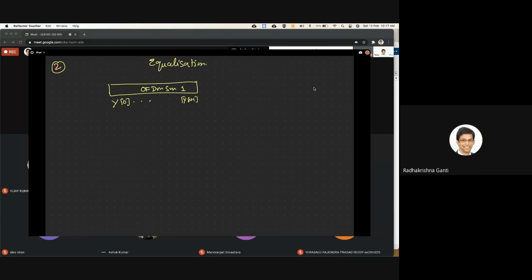Finally, you are transmitting it. When you transmit it, it is actually going through a multipath channel. It's an LTI system, a channel with a certain impulse response, some h of n, h1 to hn, some sequence. What you get at the output of the channel is not circular convolution, but linear convolution.